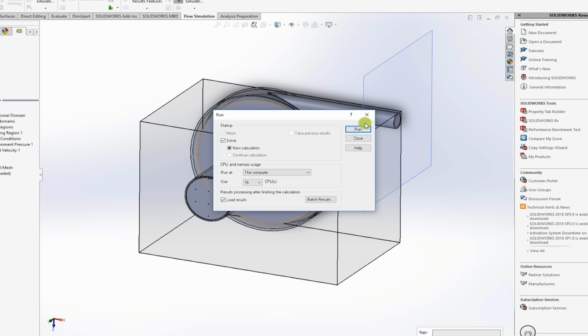If I run this calculation as it is, the simulation is going to converge very quickly. That is because convergence is checked by looking at the equations and seeing if LHS minus RHS is equal to 0. That is what convergence criteria means. This sometimes can be very misleading, and it can lead to a quicker solution. The solutions would still satisfy your equations, but the solution has not yet developed.